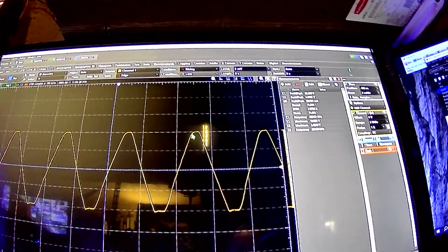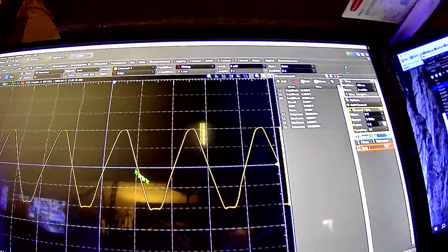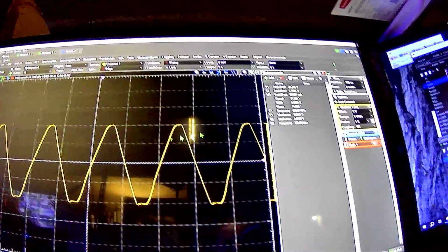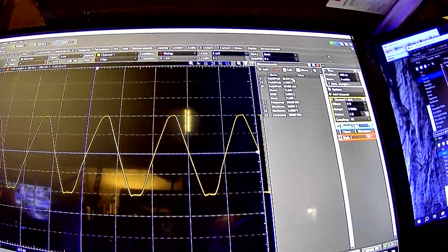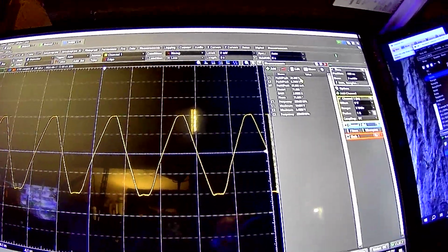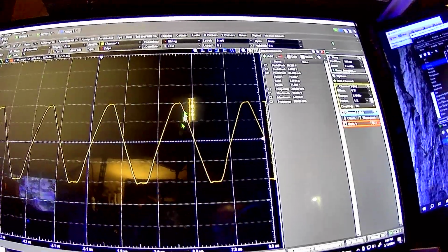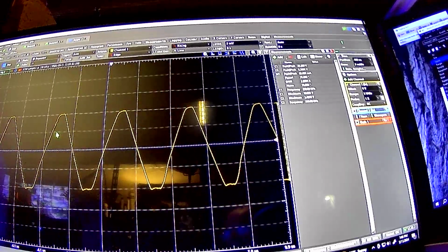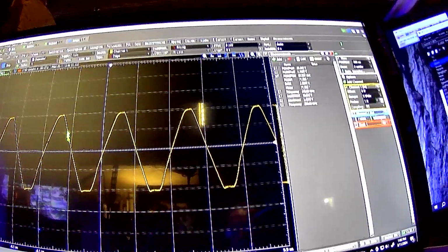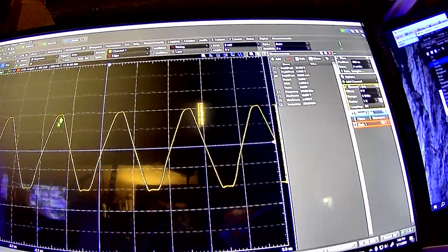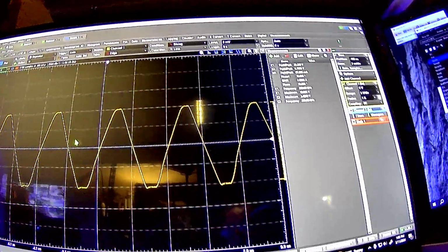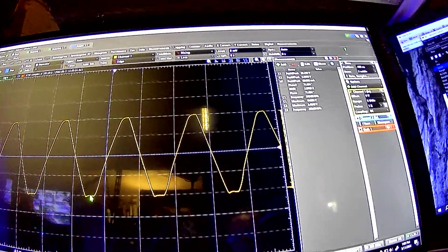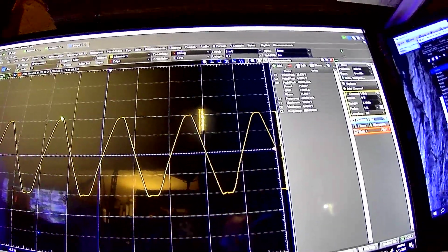By putting a square wave into it, you're seeing the maximum signal rate coming out of a DAC that this could handle at full power bandwidth, 20 volts peak to peak. This is the maximum signal you could generate out of a 500 kilosample DAC, and this is how this device would handle it. It doesn't look like a square wave, it looks more like a triangle wave with flat tops and bottoms a little bit. But that's the best you could do, going from rail to rail.